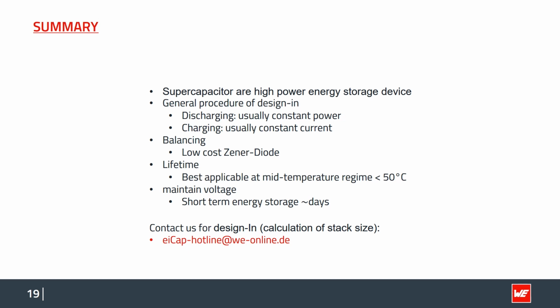For the balancing, I recommend always the Zener diode. Concerning the lifetime, the supercaps are best at the mid-temperature regime, let's say below 50 degrees Celsius, if they have to last for, let's say, a couple of years.